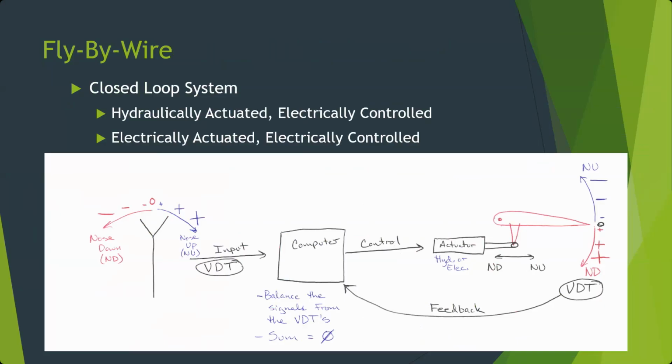It's going to move the flight control right up till it gets to the stall point, but it's not going to actually keep nosing up until the plane stalls. Compared to a Boeing, if you pull all the way back, it's going to just keep nosing up. They didn't use that at first. They do now. They have more control laws in place now. Okay.